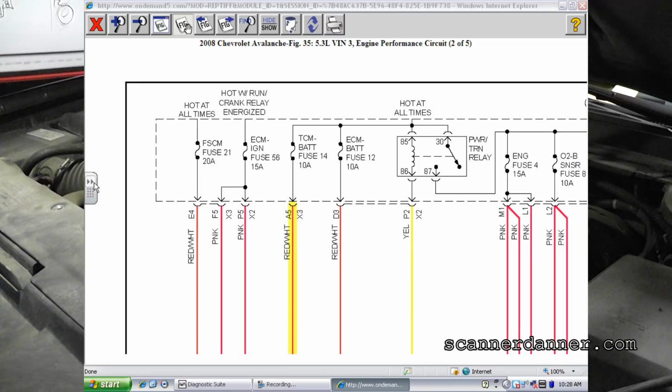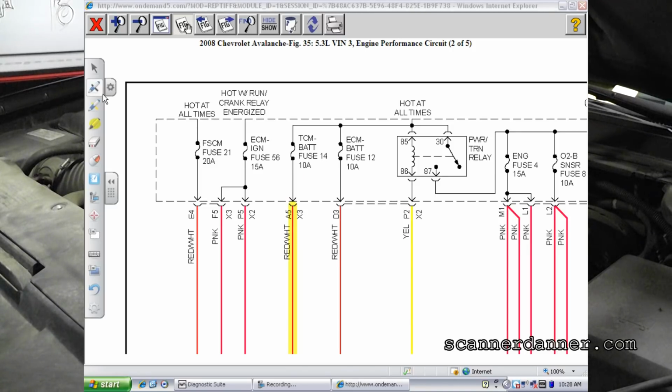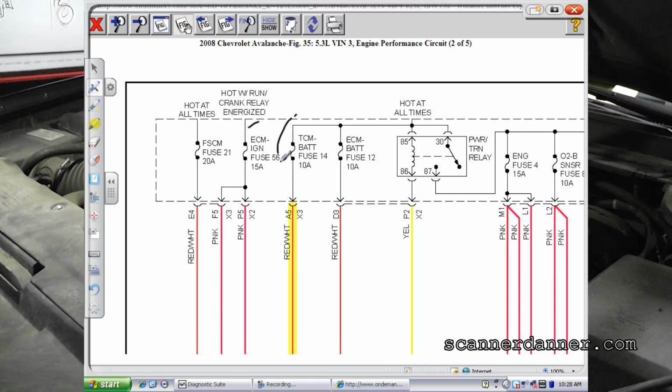What's this tell us right here? This is all we need, guys. Right there. What's that tell me about this solenoid? I don't know where the white wire goes yet. Red-white wire goes to a fuse, means the white wire has to be what? Ground. And we know the computer controls the solenoid, so where's the white wire go? To the computer. This is ground side switched, just as we thought. So again, going into this,